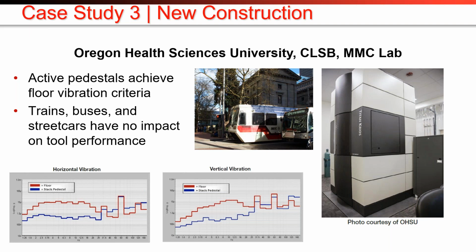So just highlighting that the real critical vibration frequency range is about 0.5 hertz to 30 hertz. Above 30 hertz doesn't really matter. Below 0.5 hertz doesn't really matter either, because everything tends to be moving together as a rigid body.